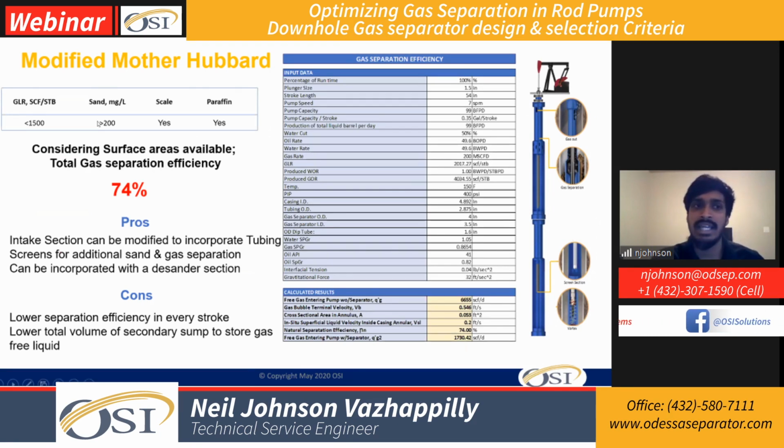But like I said, this separator design with just a 48-foot, or maybe a 72-foot, having an additional Mother Hubbard can help in low to medium GLR wells. By low to medium, I mean close to 1500 GLR or below.